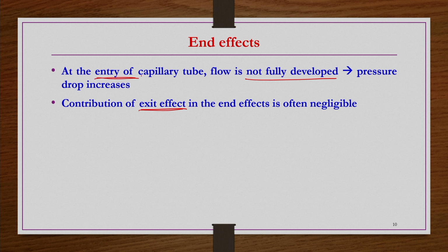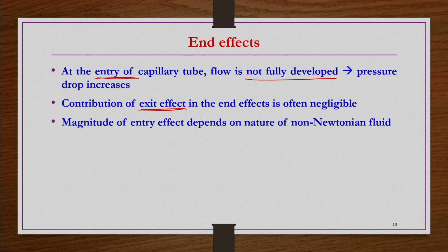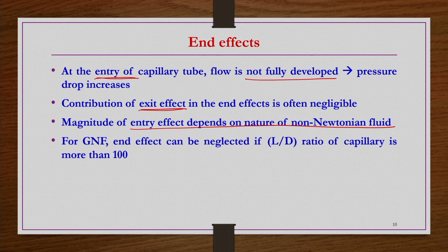So, then we have to do appropriate considerations. The magnitude of the entry effect depends on the nature of the non-Newtonian fluid that we are working with. Whatever we are going to see now is primarily for time independent non-Newtonian fluids. For generalized Newtonian fluids or time independent non-Newtonian fluids, if you have L by D more than 100 or 150, these end effects are more or less taken care of, and you can be safe. You do not need to worry about these end effects.